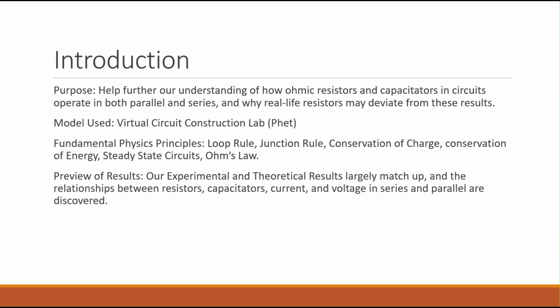The purpose of this lab is to help further our understanding of how ohmic resistors and capacitors in circuits operate in both parallel and series, and why real-life resistors may deviate from these results. The model we're going to use is the Virtual Circuit Construction Lab, which is PHET. Some fundamental physics principles are the loop rule, junction rule, conservation of charge, conservation of energy, steady-state circuits, and Ohm's law. Our experimental and theoretical results largely match up, and the relationships between resistors, capacitors, current, and voltage in series and parallel are discovered.